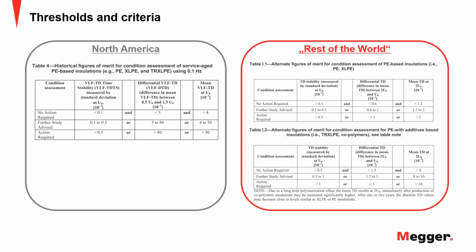That depends really on the individual phase, because it could be that one of the phases has maybe a latent manufacturing defect that eventually will cause these issues, or it might be it was damaged at one point, even on a three-core cable. Sometimes it gets damaged on one side and that hits the one phase.